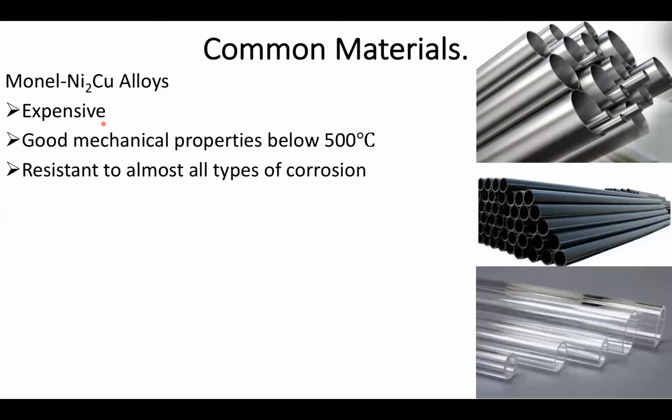And it turns out that it's almost entirely corrosion resistant. However, watch out, you may need some other materials once you get to high temperatures. But if you're looking for something that's kind of the benchmark of corrosion resistant, you're looking for Monel, and that's actually this picture here on the top. You may have mistaken it for other kinds of metals in the past.